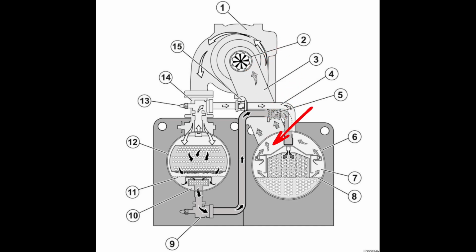Now, depending on our compressor, we may or may not even want that oil to get there to begin with. So with a centrifugal, we don't want that oil to be able to get to the impeller to begin with. We want this to be as clean of a refrigerant as possible. With a screw compressor, on the other hand, it's okay if we do get that oil up into our suction line, and that's an okay process.